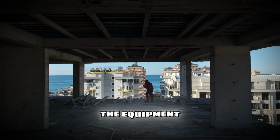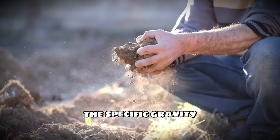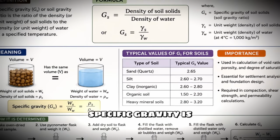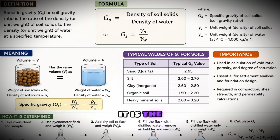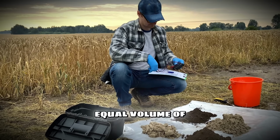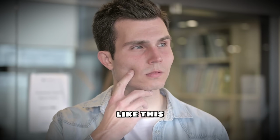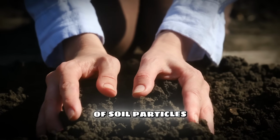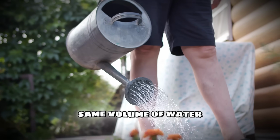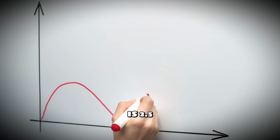Before we touch the equipment, let's define the concept simply. What exactly is the specific gravity of soil? In the simplest terms possible, specific gravity is a ratio. It is the weight of a given volume of soil solids compared to the weight of an equal volume of pure water at a specific temperature. Think of it like this. If a handful of soil particles is exactly 2.5 times heavier than the exact same volume of water, the specific gravity of that soil is 2.5.